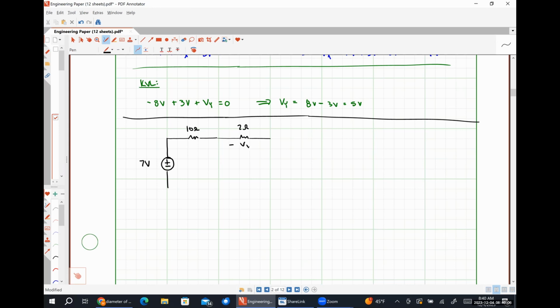So this will be Vx with negative polarity on the left. And then let's put a dependent source here. Let's make this 2Vx, like so. What we're going to wind up doing is using a combination of Kirchhoff's voltage law and Ohm's law in order to solve for the quantity Vx in this circuit. Let's just put Vx is equal to question mark to remind us of what we're solving for.